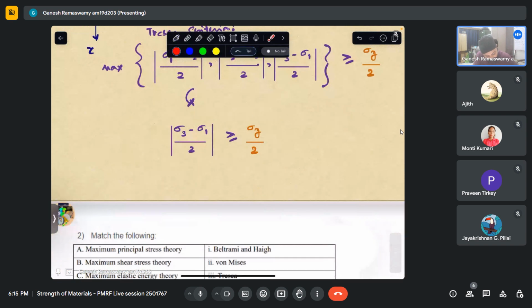Now, this is the limiting condition that we have been given for the material. This is a function of the actual stress that has been applied, but we don't want it to always reach the peak stress. So we would also want to bring in some factor of safety, factor of redundancy, because of many other parameters about which we are ignorant.